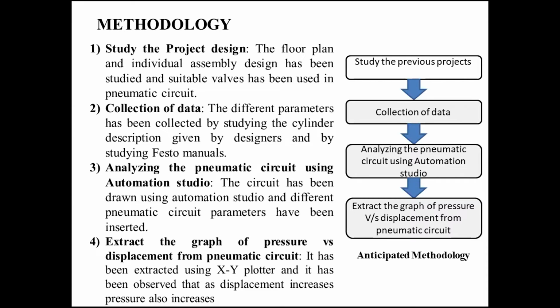Analyzing the pneumatic circuit using Automation Studio. I have used the Automation Studio software to analyze the circuit and draw the different circuits. Then I extracted the graph of pressure versus displacement from a pneumatic circuit. There is an option called XY plotter, because pressure is one parameter and displacement is another parameter. So there are two axes, and the plot has been obtained subsequently.